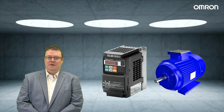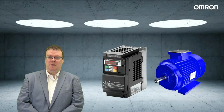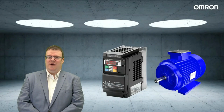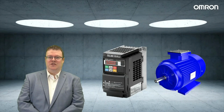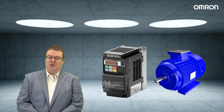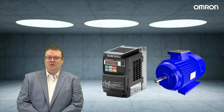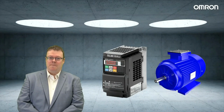Inverter drives are used in a wide range of applications in industry, be it controlling fans, pumps, conveyors, machine tools, virtually every application. They offer a number of advantages over more traditional methods of starting and controlling motors, such as a direct online or a star-delta starter. Essentially, an inverter drive lets you vary the speed of the motor.